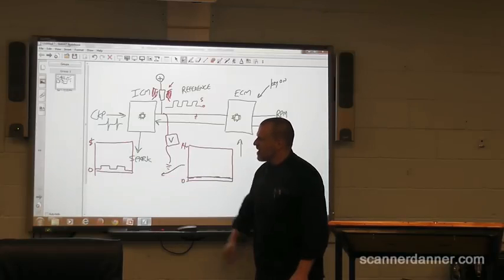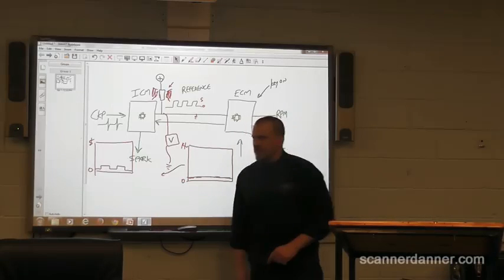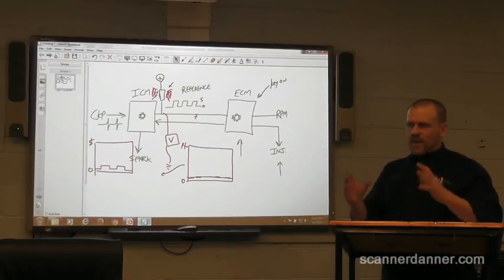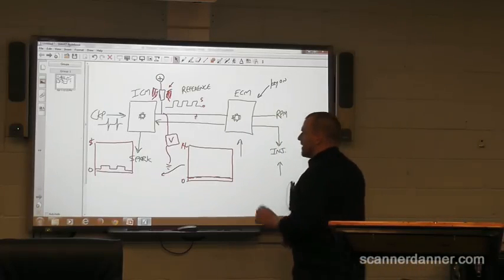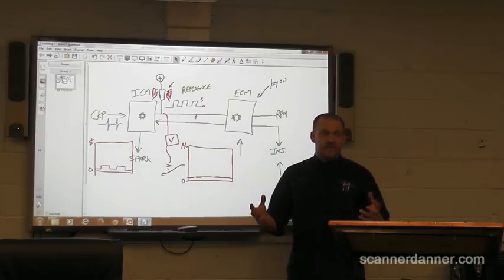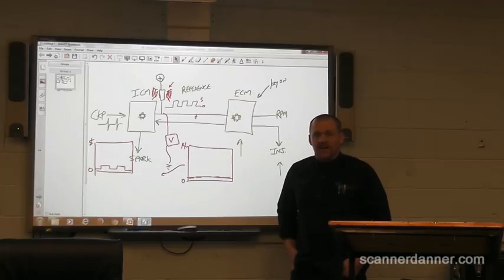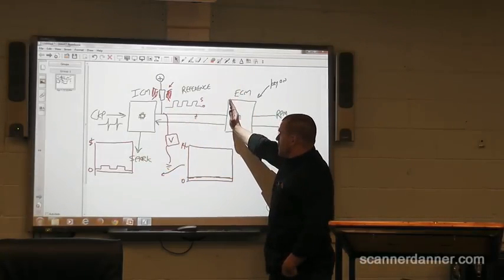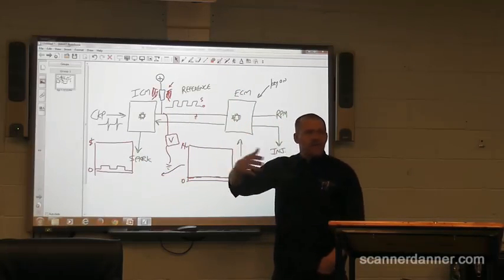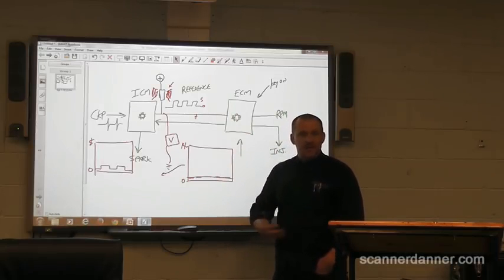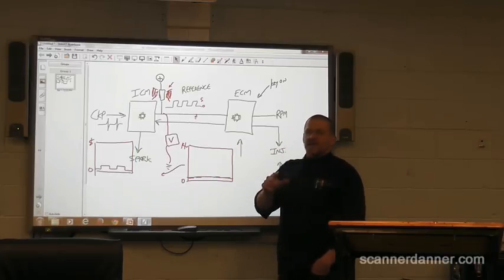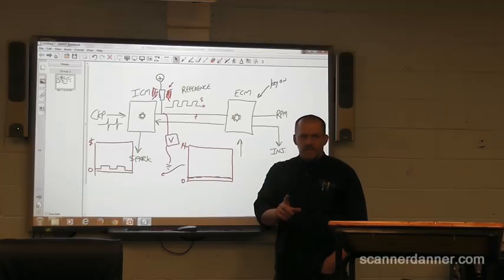So there's something there. And after I saw that, I thought, well, maybe there's resistance in the circuit, or I don't remember my next step, but I definitely am going to now. Really this is where the manufacturer flowchart would have been better. Manufacturer flowchart would have had you disconnect the module, disconnect the computer, and measure the wire for opens and shorts. And that's really what we need to do at this point. So this will be a good review of that. My concern is not an open. And you guys will learn this as we go, and I'll repeat this over and over.